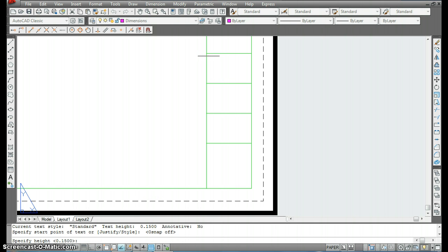We're going to put really small letters, and those are going to be 0.05 in size. I'll hit enter. Angle of rotation for this we can do 0, and I'm just going to type in drawn by, with a colon after it, enter, enter. And once again, I didn't pick a great spot there, so I'll just move it, highlight it, grab it, pull it in just a little bit. And then underneath here, you're going to put first initial, last name for yourself.